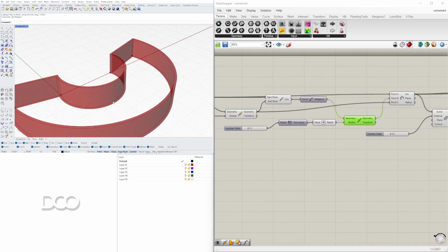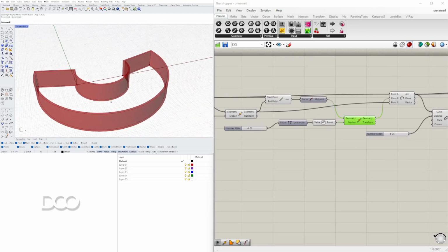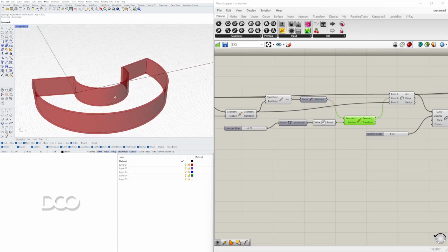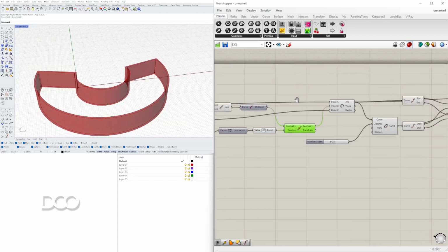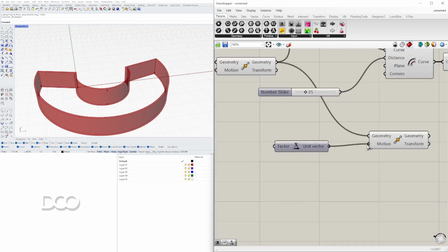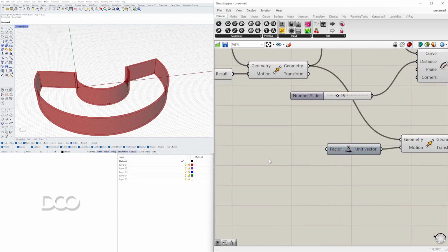that was moved in, now we can use that to create the line that's going to be extruded to create that opening. So I'll go here to move, and we're going to move this point in the X direction. We'll go here X or unit X, and then we'll plug in a value, let's say 4.5.